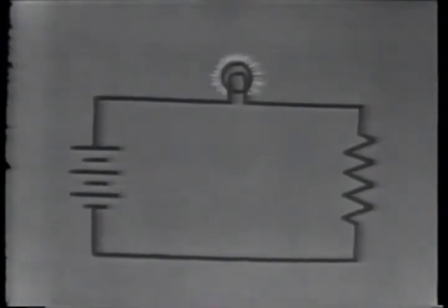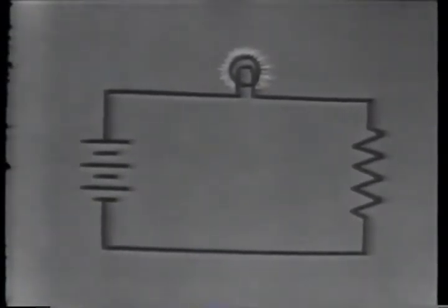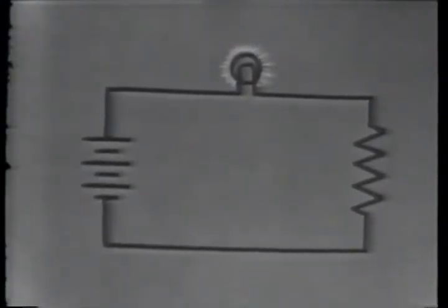Now let's take this idea a step further by analyzing what would happen when another circuit component is connected in series with a shorted one. This circuit is designed to light a lamp. Since the resistance of the lamp is normally low, a resistor is connected in series with it to control or limit the amount of current flowing through the lamp.